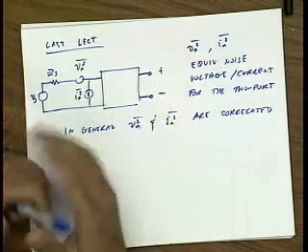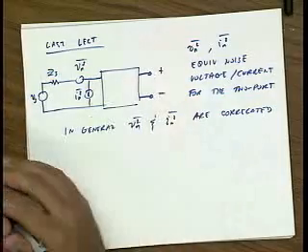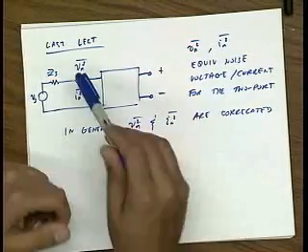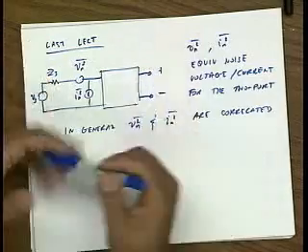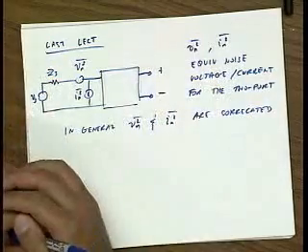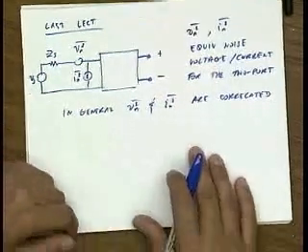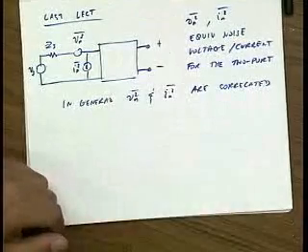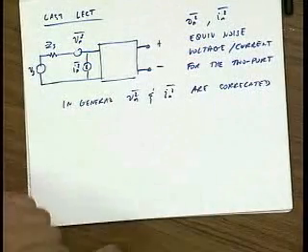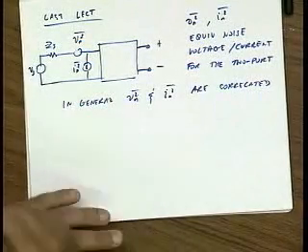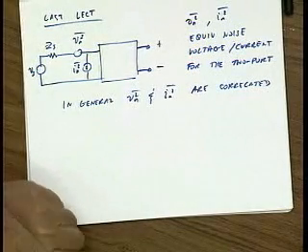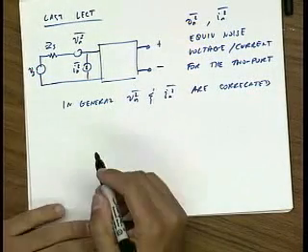If you look at the number of parameters, there are 4 parameters that characterize your 2-port: Vn, In, and a complex number. So 4 real parameters. Okay? So let's quickly go through the derivation, or maybe not so quickly, of the noise figure of this 2-port, and let's try to take into account the correlation coefficient.